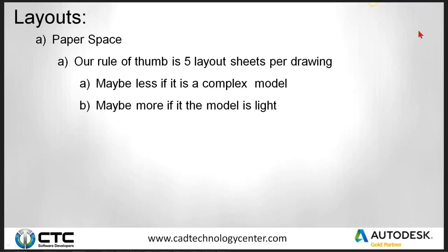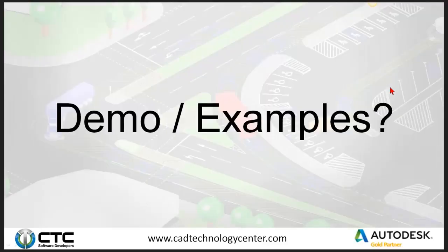So we'll go ahead and we'll jump back into things. So again, layout space, 5 layout sheets per drawing. If it's only layout pages, you don't have anything in model view, you could probably get a little bit more. Definitely utilize the sheet set manager, helps keep all your layout sheets organized. So what I'm going to do is some demos or examples of what I'm talking about here.